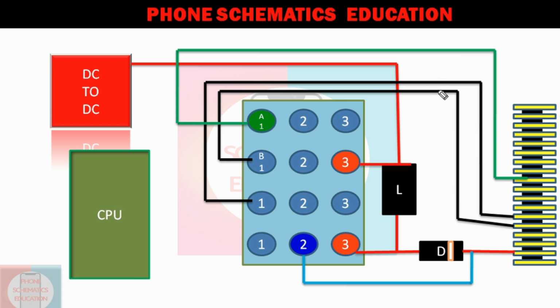Clear? Now the biggest problem that comes in the light section, where you see there is no light, is damage to the anode line. 99% of the time you will see the problem through this line. Whenever water comes into contact with the display connector or the light section in waterlogging, somehow the water contacts the light IC or light circuit or display connector.